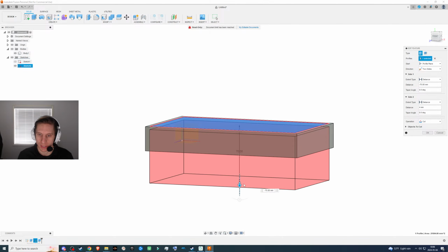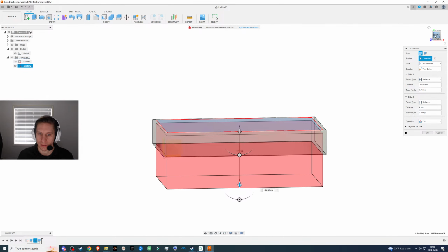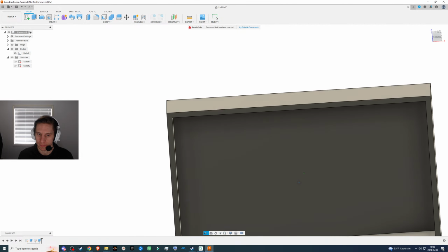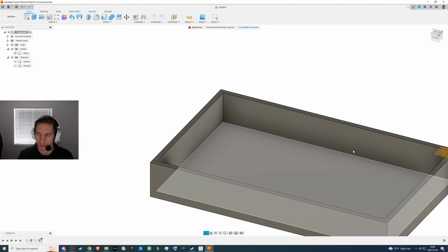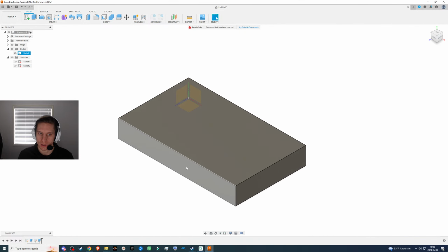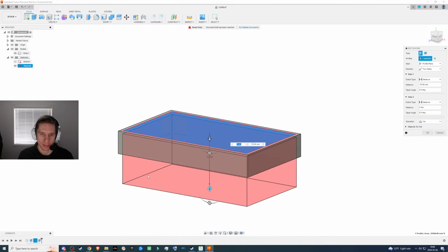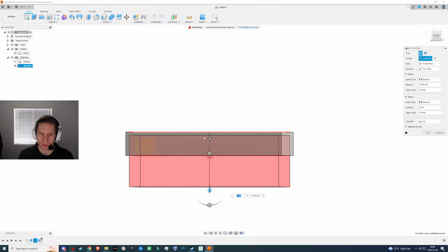But you can see what it's doing here is, let's go to the side profile view. You can see that what we've done is now when we do this, we're looking at it face up. Because what we did was we did it two-sided. We said start 4 millimeters down and extrude 70 millimeters in that direction.